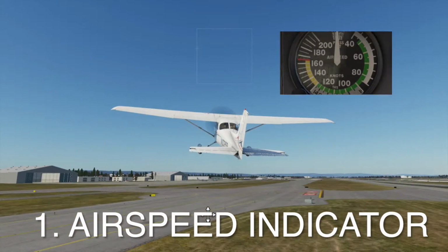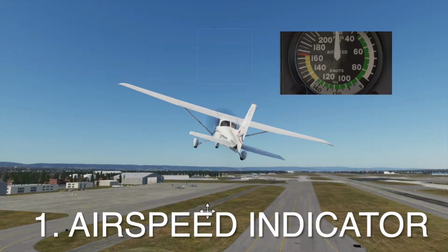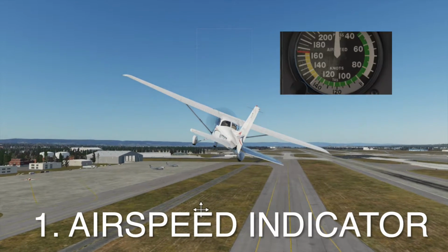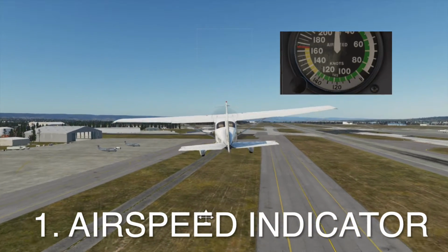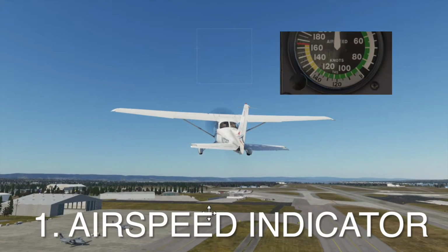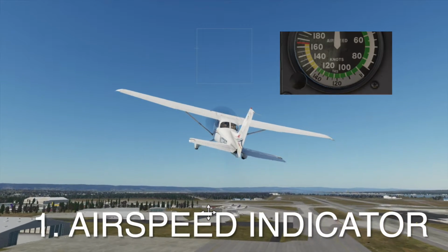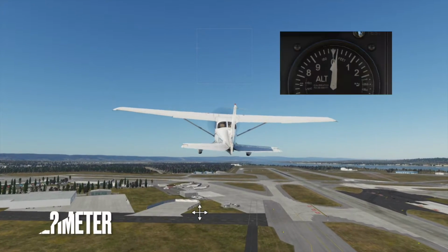Maintaining proper airspeed is crucial for aircraft stability and control. Flying too slow can result in a stall, while flying too fast can lead to structural damage. An interesting fact about the airspeed indicator is that it measures indicated airspeed, IAS, which may differ from true airspeed, TAS, due to factors such as altitude and air density.